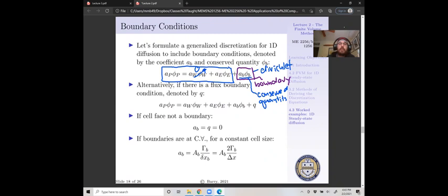If we were looking at control volume 5, we would set A east phi east to 0 and then populate those of our boundary. It's just a way for us to note that when we are on a boundary and we don't have a cell exterior to our domain, we should be treating our coefficient differently than we've treated A west and A east.